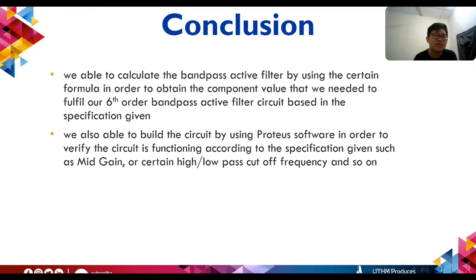In conclusion, we are able to calculate the bandpass active filter by using the certain formulas in order to obtain the component values that we need to fulfill our 6th order bandpass active filter circuit based on the specification given. And we are also able to build the circuit by using simulation software, which is Proteus, in order to verify the circuit is functioning according to the specification given, such as the mid gain or the high and low pass cut-off frequencies and so on.